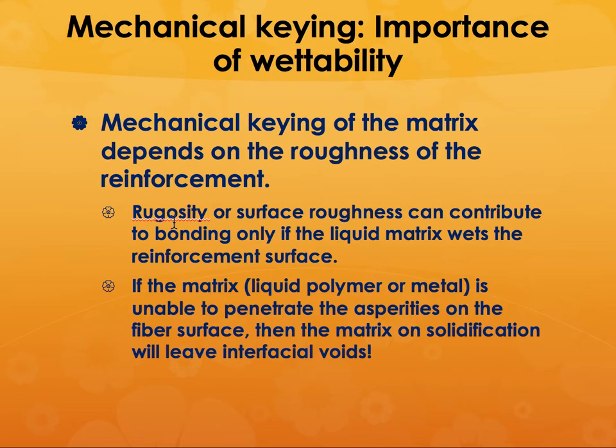The rugosity, or the surface roughness, can contribute to bonding only if the liquid matrix wets the reinforcement surface. If it is unable to penetrate the different regions of the fiber surface, then all you are going to have are interfacial voids. You don't want to have that kind of a situation.